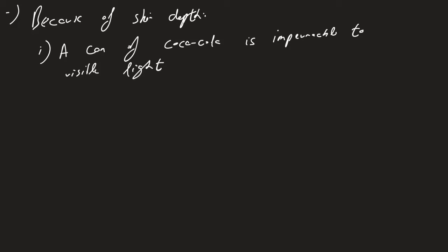So what you have is a thin coating of aluminium or tin. I'm not entirely sure what metal it is. It's one of the two, or an alloy. Because the thickness of that coating is much greater than the skin depth of optical frequencies, the light attenuates, and so you don't get any significant transmission.